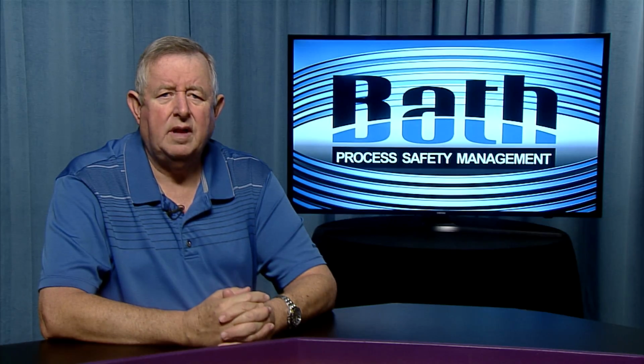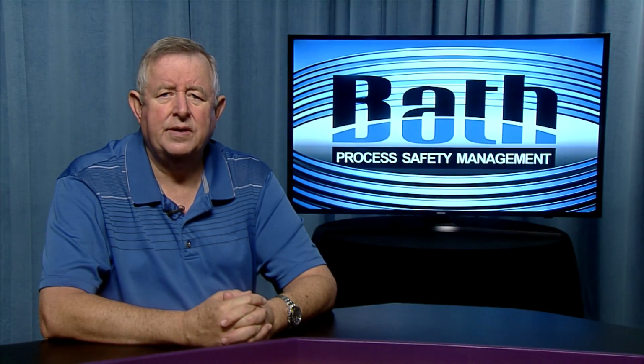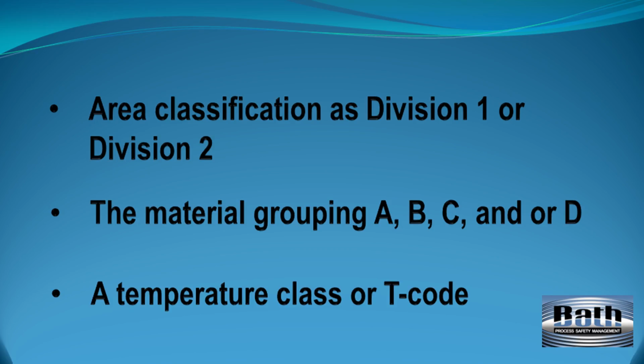The hazardous area classification study can now be performed for the interior and exterior of the analyzer building once answers are obtained for the questions just presented. The study results should again provide an area classification, material grouping, and T-code designation for all normal arc-producing electrical devices located both inside and outside the building.